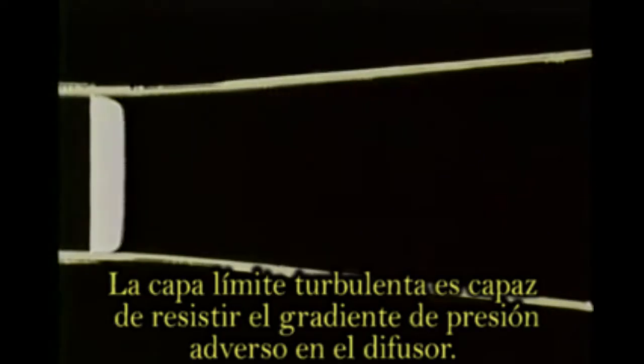In this diffuser, which was used before, we have made the bottom boundary layer turbulent by inserting a trip rod upstream. The turbulent boundary layer is able to withstand the adverse pressure gradient in the diffuser, while the laminar layer along the top wall is separated, allowing reverse flow. These timelines show that in the turbulent boundary layer, there is no separation. The overall flow is downstream.